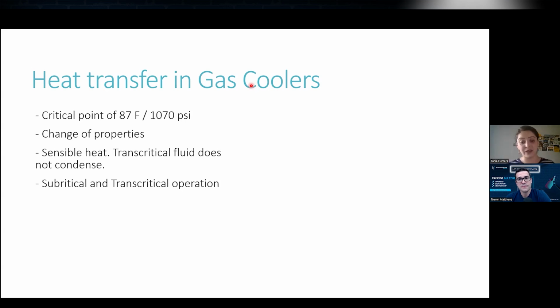And this has a very big impact, because I have seen that, for instance, if I run a gas cooler, I will have, I don't know, let's say 10 psi of pressure drop. But while running it as a condenser, the pressure drop will be higher. And this is because of the properties. So this is very important to take into account, because it will have an impact on your entire system and also in your compressor. So for instance, some customers...